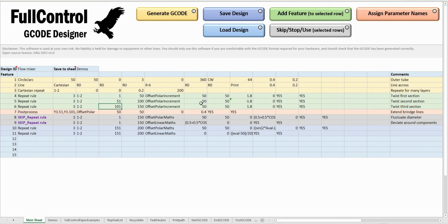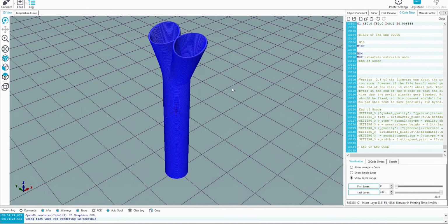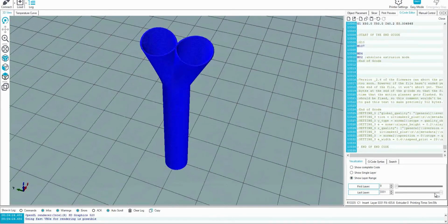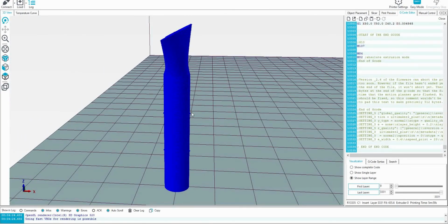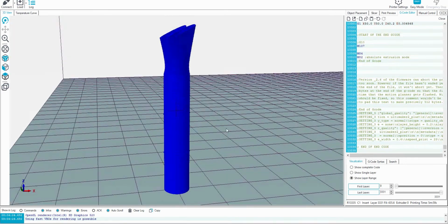So if you were to produce this design and share it with someone, there is no chance for errors to be introduced if their slicer parameters are slightly different or anything like that. This is describing every single detail that will ultimately be sent to that printer. And compared to a CAD model and an STL file, it would be extremely difficult to design a CAD model with this type of detail, and you wouldn't actually have anywhere near the amount of information. So we wouldn't be able to describe the order in which the lines are printed, the fact that we want these bridging ones to be slightly longer.